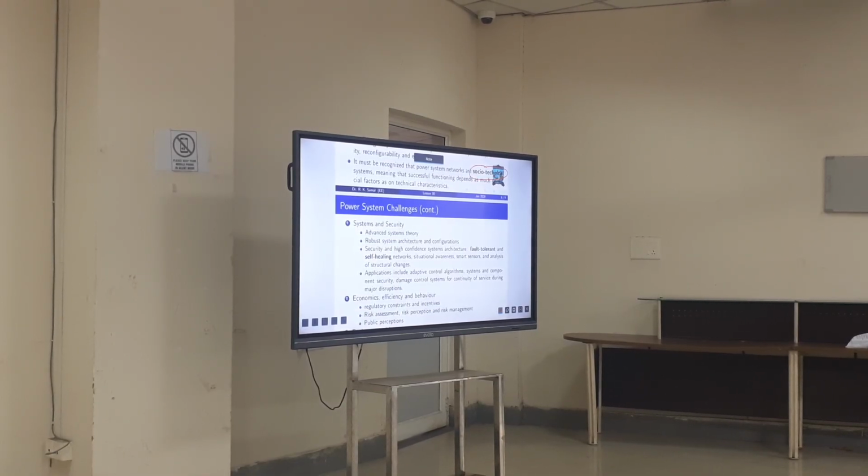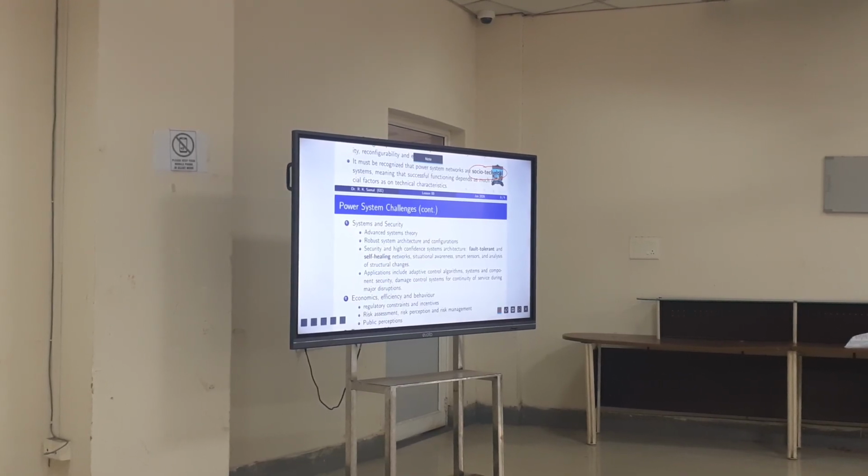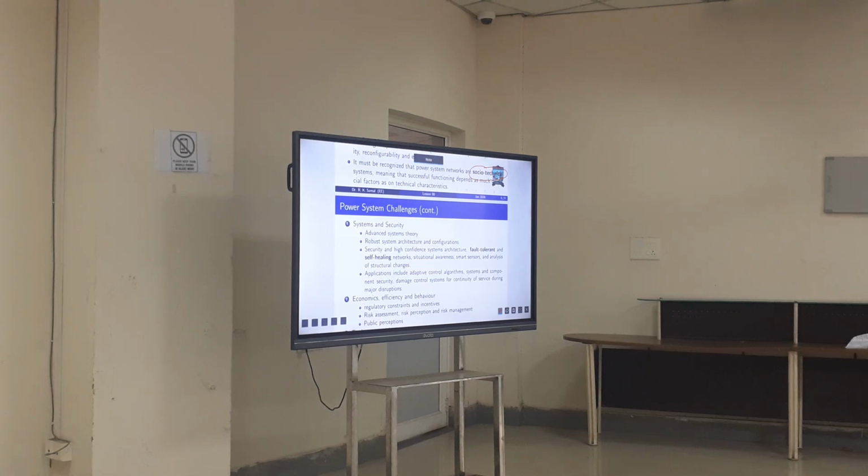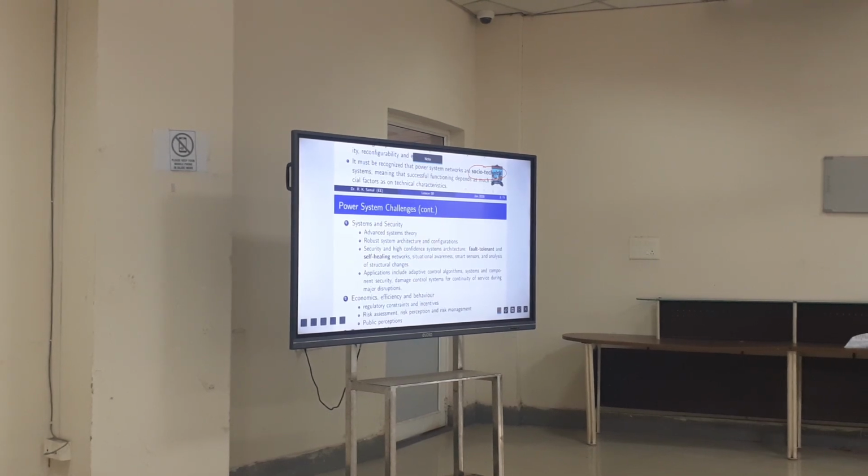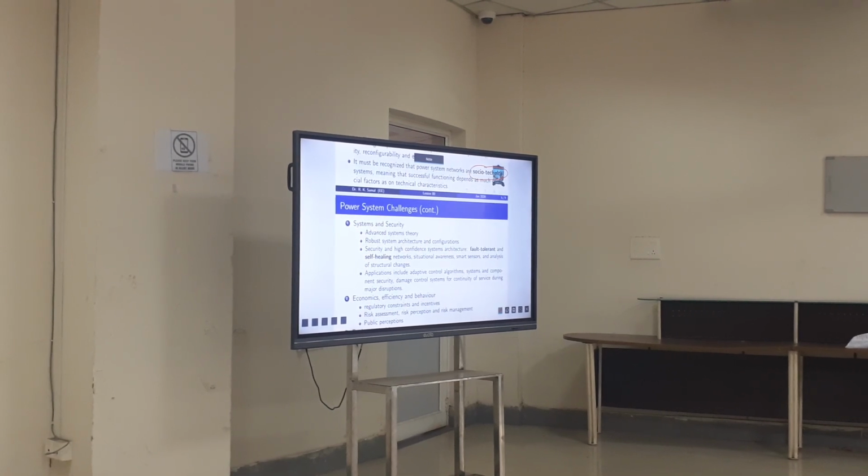For example, during the previous day when the vehicle was not charging, the solar generated, suppose, 2 kilowatts into 5 hours, 10 kilowatt-hours of energy. 10 units of energy generated. So that's about 25% of the vehicle charge. Right? So the solar PV system can provide more than the energy needed for charging the vehicle, but it may not provide the exact amount of power. Fine. So for that power, the person will take from the grid.